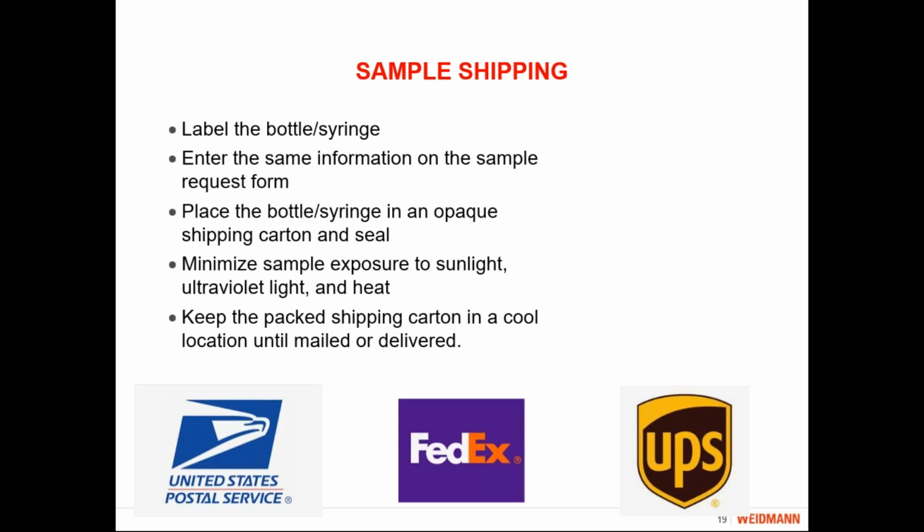You should also at this time fill out your sample request form that has that same identifying information on it, along with selecting what tests you want performed, any notes that you want to advise us from, any comments that you want to make. You want to have the address and the contact information of who the sample results should be sent to. You want to give us equipment ratings, because for oil quality, equipment ratings are important. So we want to know, for example, if it's a transformer, what the KV rating is.